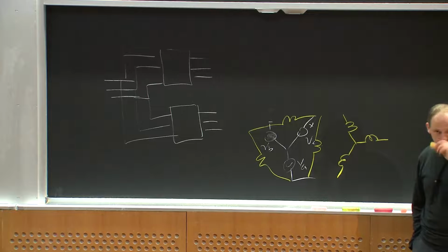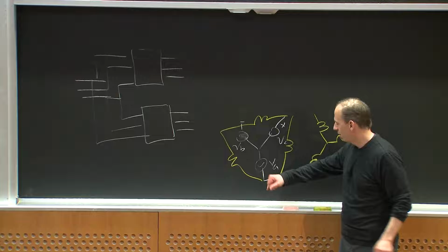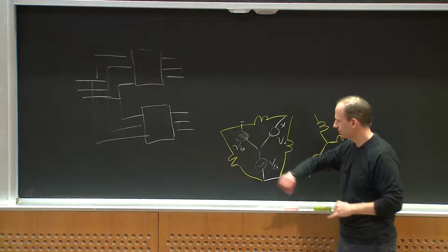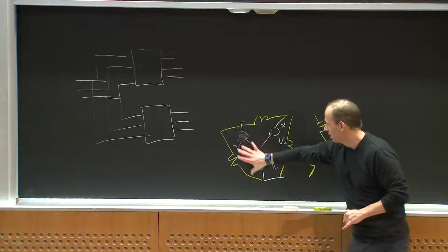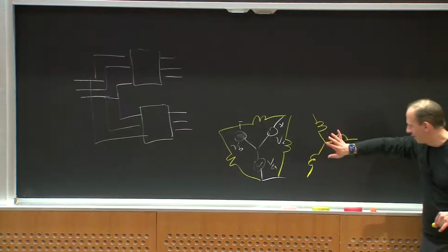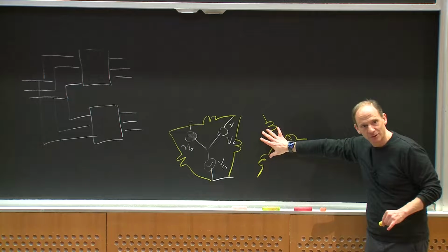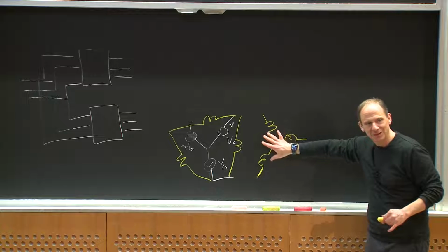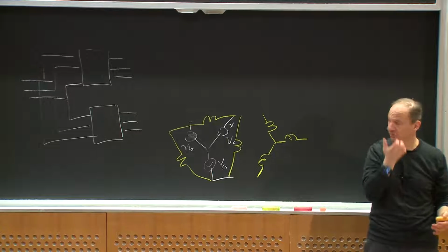So what that's going to mean is, if I have my fundamental of this set, when I run it through the transformer and get the 1 over square root of 3 scaling I want, I get another set of 3-phase voltages that are 30 degrees shifted. Okay? So now I have 2 sets of waveforms that are 30 degrees apart.